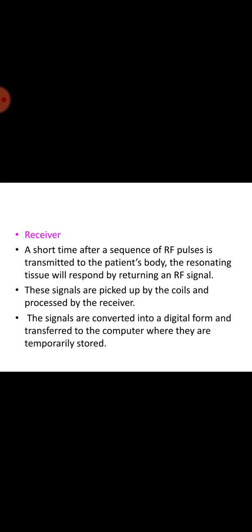RF shielding case. So for magnetic fields in the range of 0.05 to 2 Tesla used for imaging of the human body, the resonant frequencies fall in the radio frequency band. For example, in a field of 1 Tesla, H resonates at 42.57 MHz, F at 40.05 MHz and P at 17.24 MHz. Usually the resonance is extremely narrow, in the range of 10 Hz, in typical biological systems.